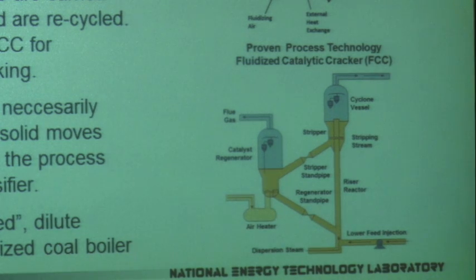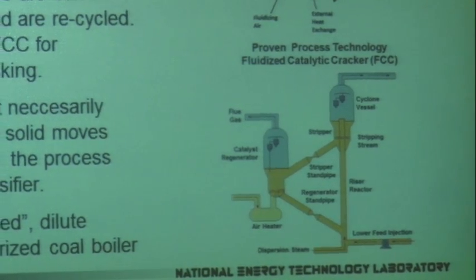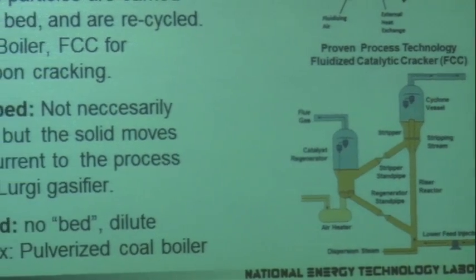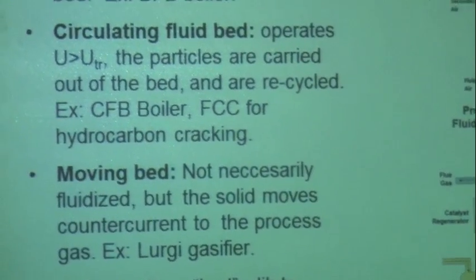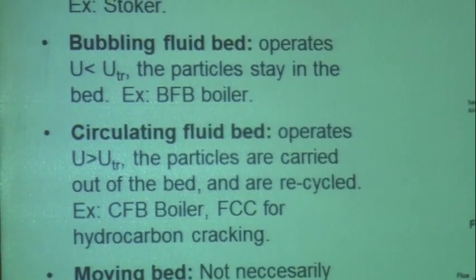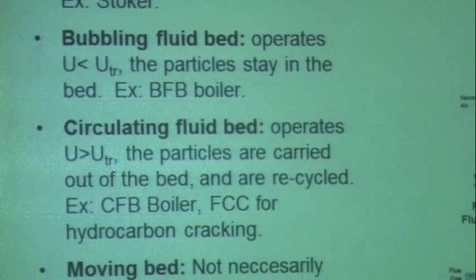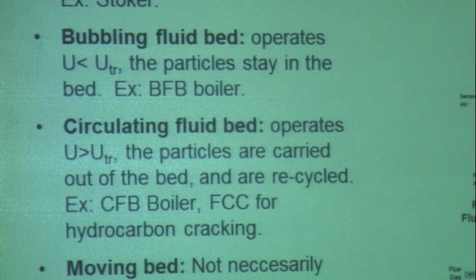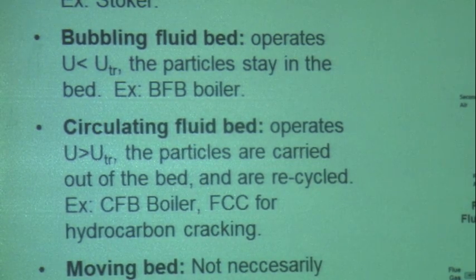So you have the highest oxygen content where you've got the lowest CO2, which is what you want to consume all that CO2, right? Counter current. And that's what you do in a moving bed design. And in chemical looping, L.S. Fan and his students at Ohio State have really honed the art of developing that as a concept for chemical looping combustion because of that counter current behavior. So that's one way you can arrange the bed.